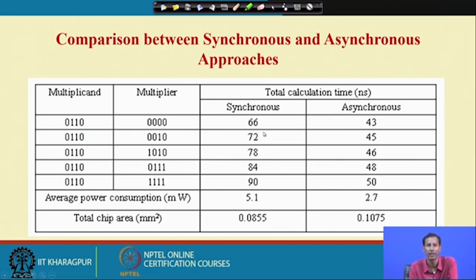I have not discussed the asynchronous circuit here, but here, in a particular clock, it is checking the LSB position of B, and then it does the shifting operation and count operation, and again it is also doing the addition operation on the same clock edge.